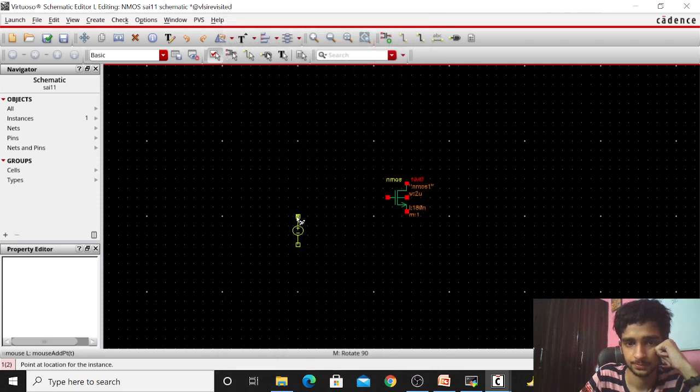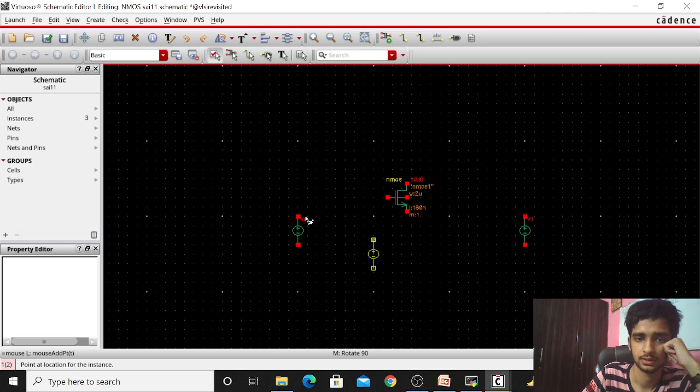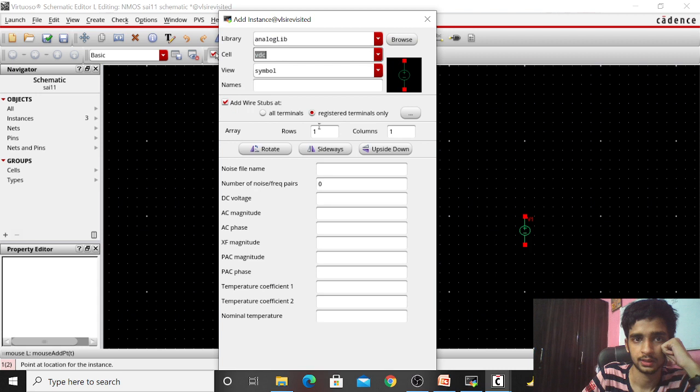So just place one VDC here, one VDC here. Why are we using it? Because we have to plot between VGS and VDS with respect to I now. That's why this is for VGS and this is for VDS. Just press escape, and then again you have to click on I.